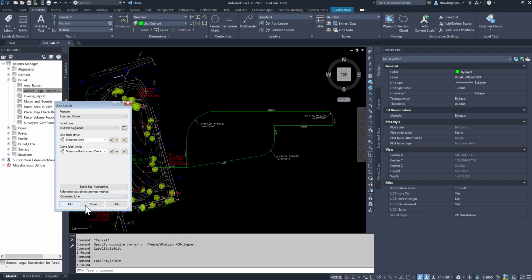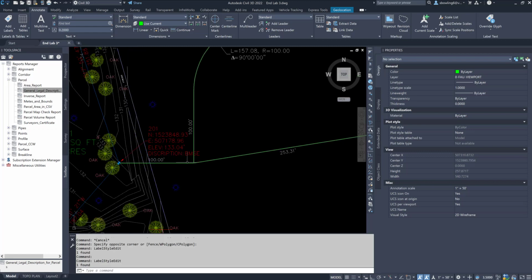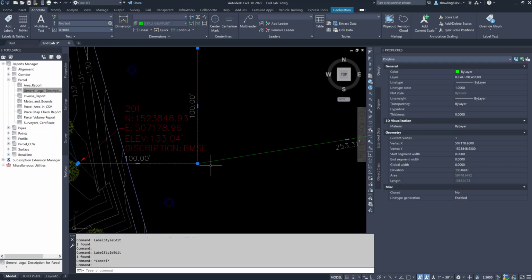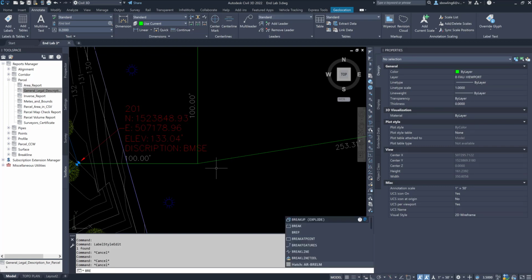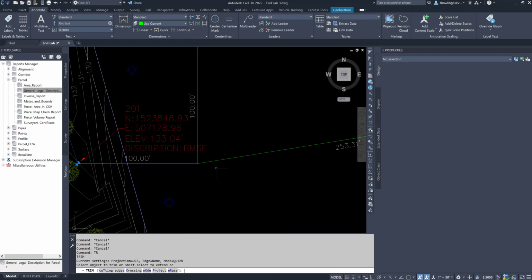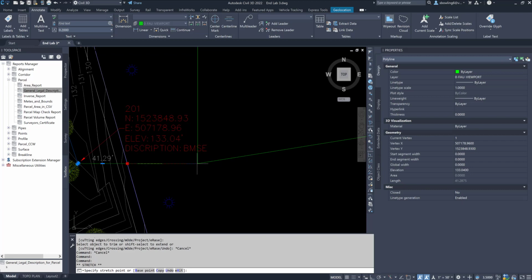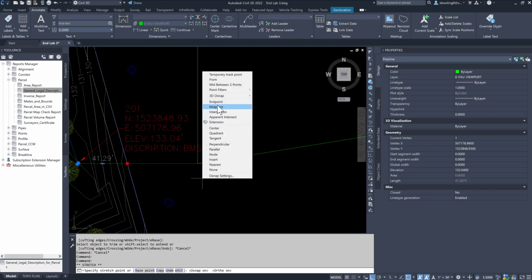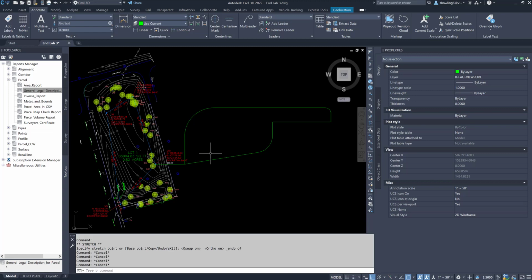All right. Now, when you do that, if I explode this, I'm not going to explode it. I'm going to trim, and I'm going to trim this off, okay? And I'm going to bring this back to just the length. F8, F. I need to hit the end point. Okay, so that's, I still want that 100 to show.